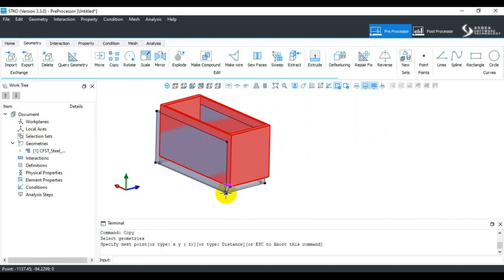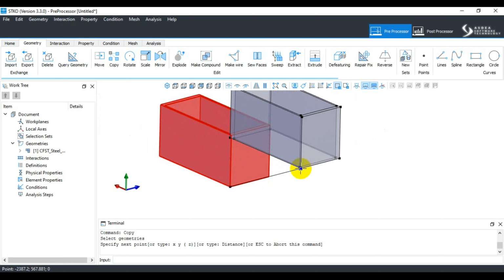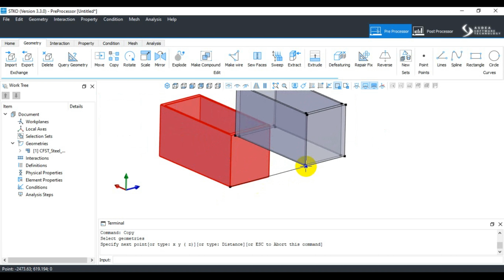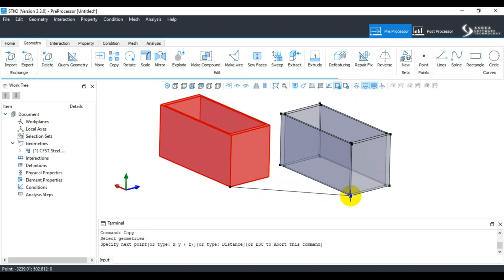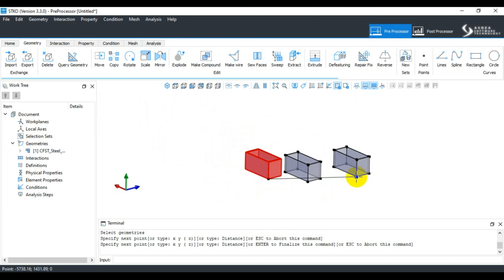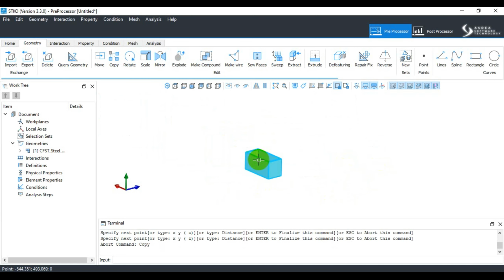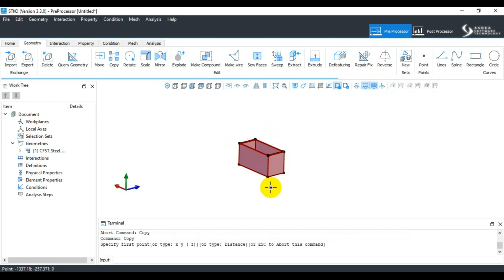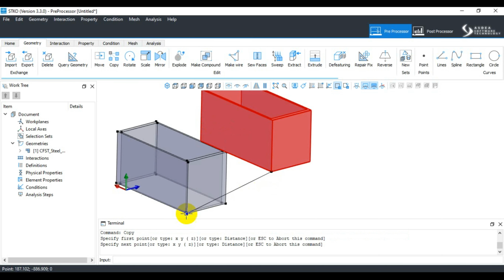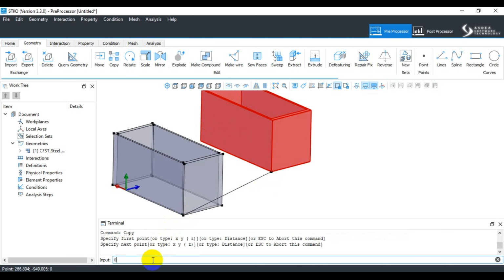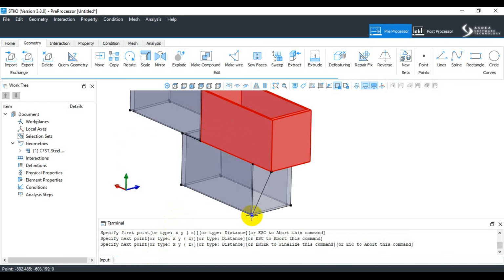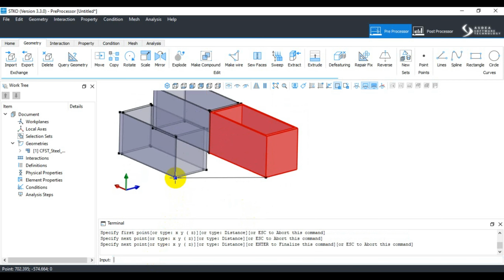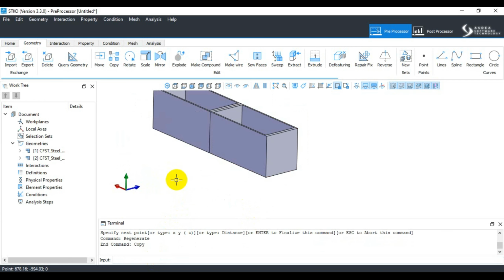So for the next option to command, I'm not repeating this here, but let's go with this option, right? First by move copying it with the GUI command here, right? I can do whatever I want with it. Then escape it, and I want to select this one again and specify the point to move it with respect to point. So let's make it 000 the origin, and we can see here that this is done here.